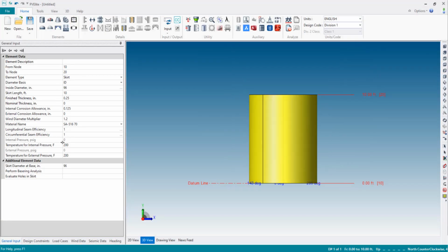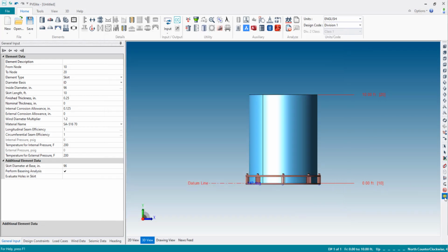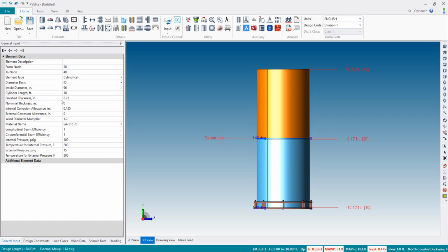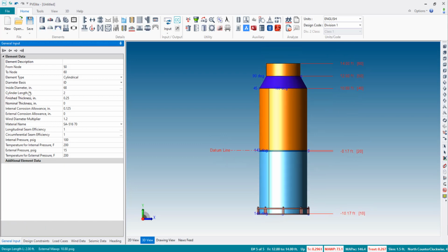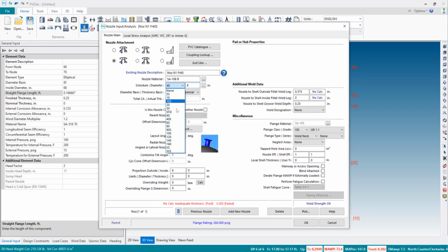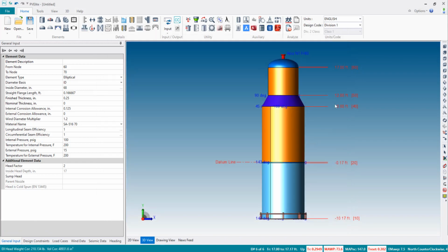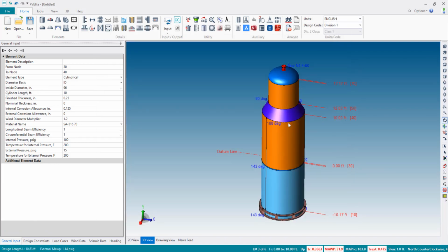Now we see a workflow that begins in PVLeet. Here, a vertical vessel with a bit more complexity is created from scratch. This is a vertical tower sitting on a skirt with a base ring. Some more details like a cone-to-shell stiffening ring and nozzle on the top of the vessel are placed. These are all details that CADWorx will be able to recognize and import with ease.